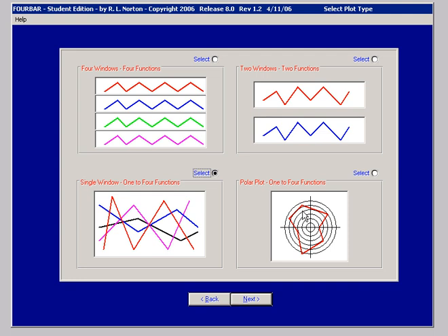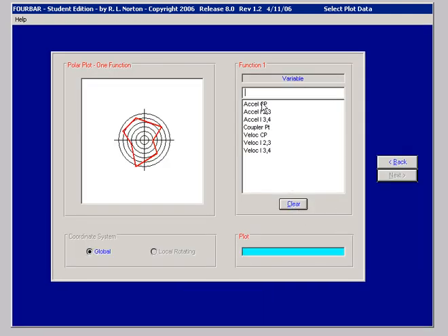Let's show you this one. This is the so-called polar plot. Now the menu is a lot smaller here. The only things that this is relevant to are vector information that are not along the z-axis, which would exclude such things as the omegas and the alphas. We're in a two-dimensional world here. Remember that all of your angular information, angular velocity, angular acceleration, they're all vectors, but they're vectors that live normal to the plane that we're investigating. That is, they're along the z-axis. So thus we can just indicate them by a magnitude. Their direction is the same in all cases.